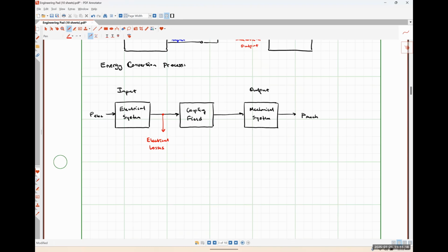So some of the electrical losses that we might see are literally the things that we've already described on our transformer, right? So we are going to have energy lost to effectively heating up our wires as they carry current. So those I squared R or ohmic losses, that is a form of electrical loss.